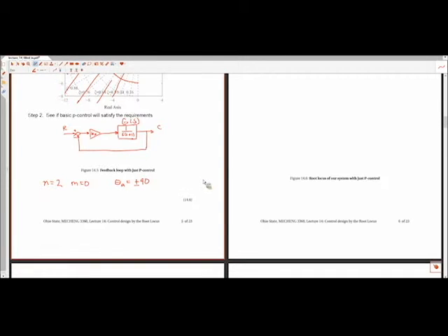That's from just this discussion of these topologies, that if we have n minus m equal to 2, then we have asymptotes that go off at plus or minus 90. Or rule 3, if you want to go by the rules, but we also learned this kind of shortcut in terms of the difference between the number of poles and zeros and how we draw the asymptotes. Okay, intersection point.